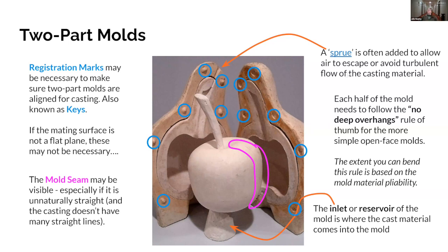And when you are designing the mold, you need to do it in such a way that it comes apart as easily as you can manage. And sometimes you need to make another part to the mold. Maybe it would be a 3-part mold. You're always going to have a line at the meeting part of the molds, and how you design your mold is going to determine how much cleanup you end up doing. So there is also, as I was saying before, you need a place to pour the material in, and you need a way to let air out.